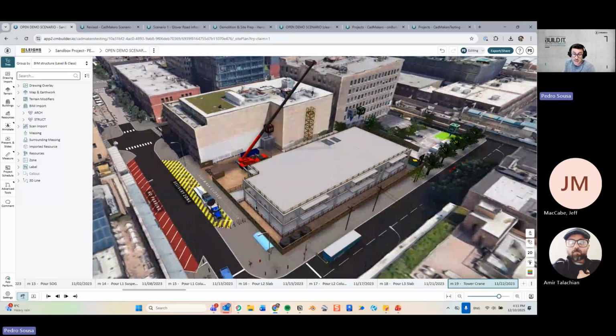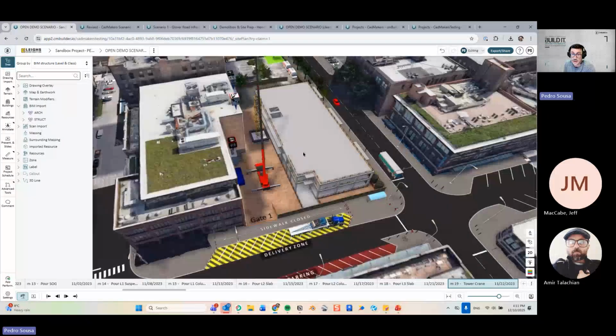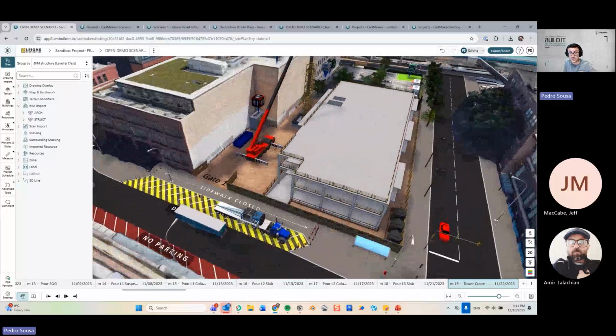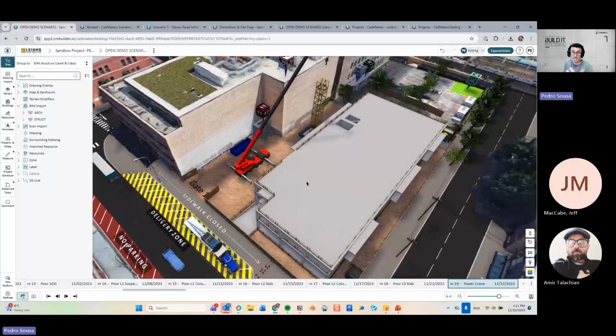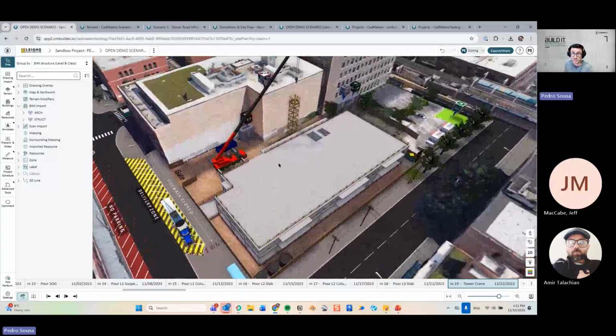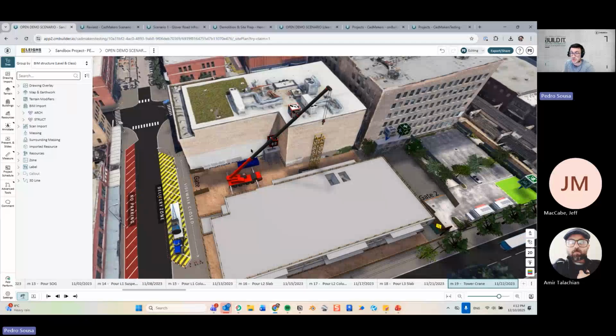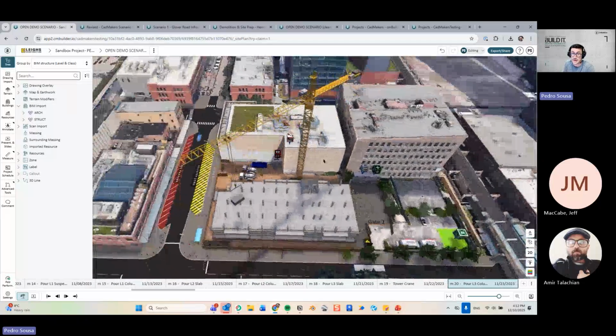And in the scene, we are seeing here the assembly of a crane, right? So this is a very challenging point in the construction stage because you're going to need to block some areas for deliveries. The whole site kind of needs to stop for that. And you need to make sure that your mobile crane will be able to make all the picks to place them in the right location.